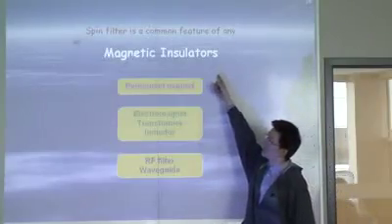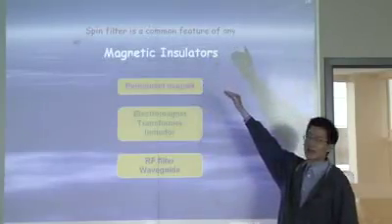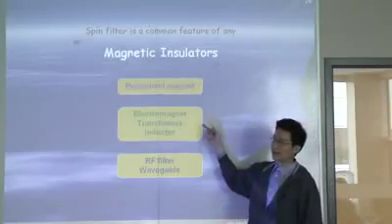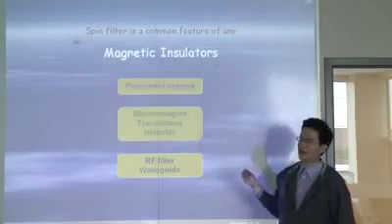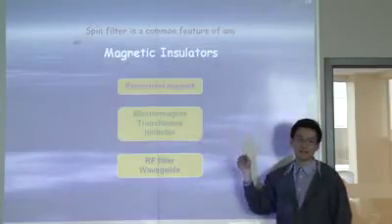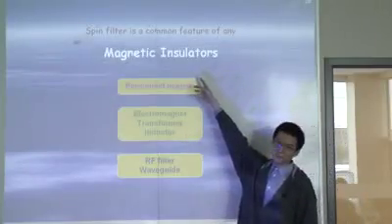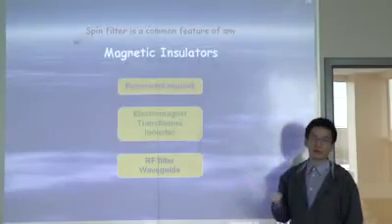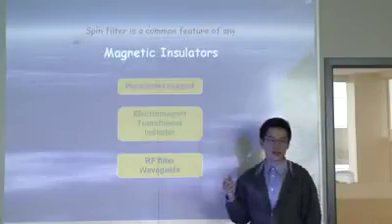And because these materials are magnetic, they have a very high permeability, and they are insulating. They are commonly used as a core material of electromagnet and transformer and inductor. Because they are insulating, when they are used in an AC operation, they will significantly reduce the eddy current loss.